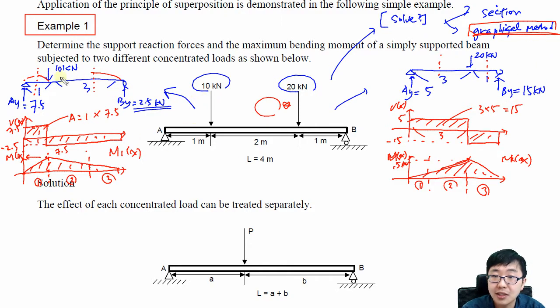So how to get that? This is your homework. In this case, you can establish your free body diagram. You have AY, and this is V and M, and there is no force applied because we cut it here before the 10 kilonewton.